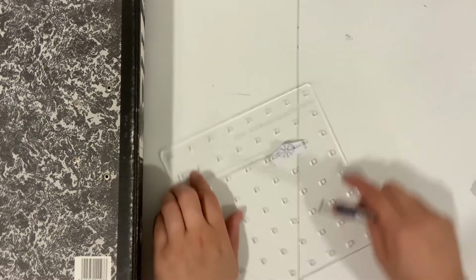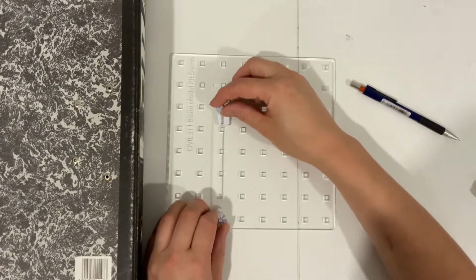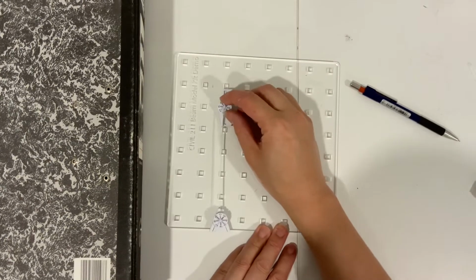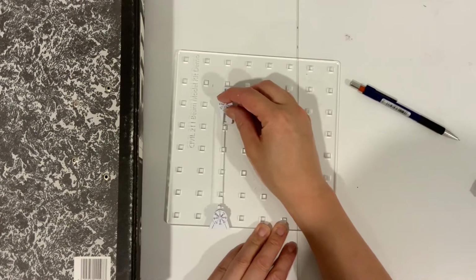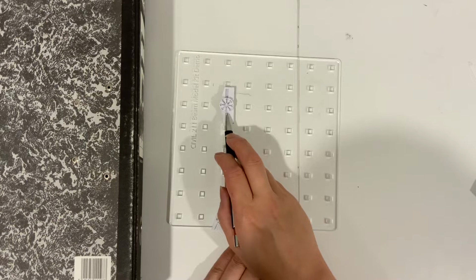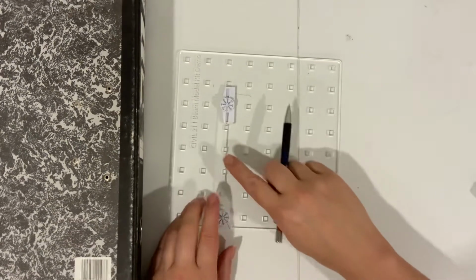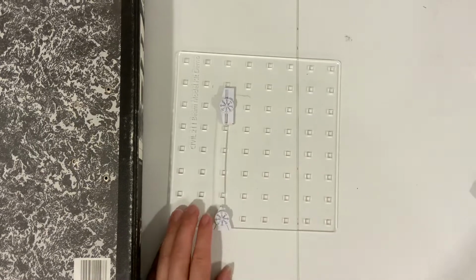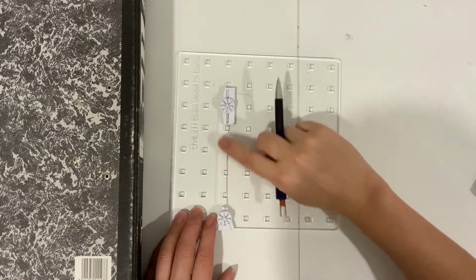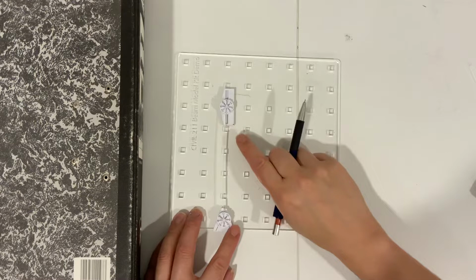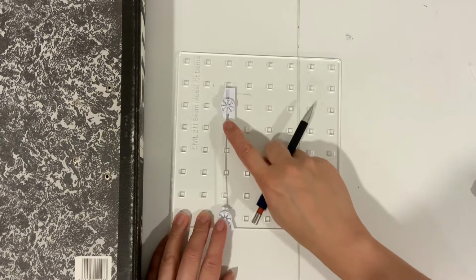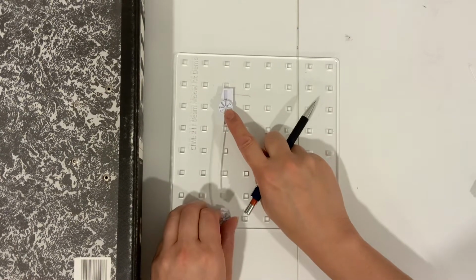Okay. Now if it was a column, as you can see here, I can apply a tension force in that direction, so I can shove a force upwards at this end here, and it's not becoming unstable, and it would just elongate with the axial stiffness, Young's modulus times the cross-sectional area of this thing here.